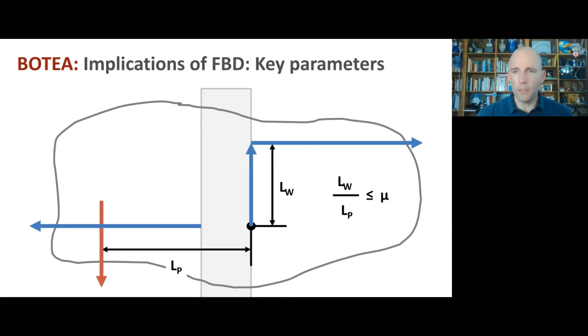The normal force and the payload force are not related, so the payload force will drop out. And noting that our friction constraint is an inequality, not an equality, that the friction force is less than or equal to the normal force times the coefficient of friction if we have static friction, not sliding, not dynamic friction, we'll get this. So it's going to be super important that we have the vertical offset of the wheels be the right distance compared to the horizontal offset of the payload.